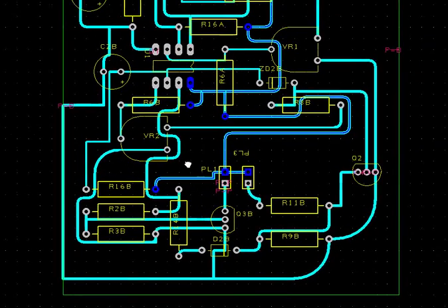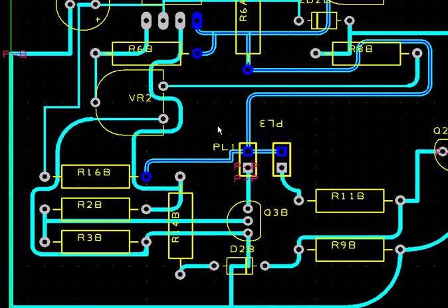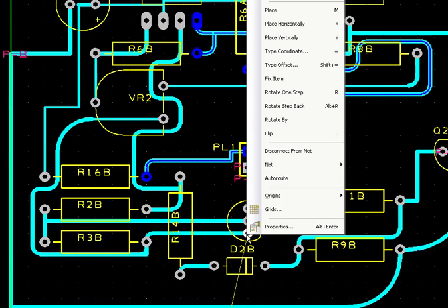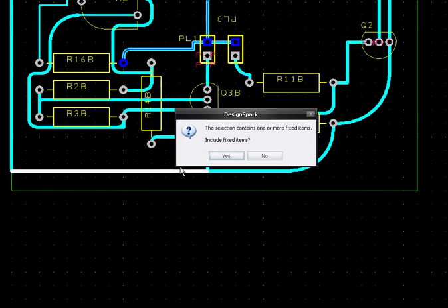So it's a bit like a game actually, but it's something functional. Right, I'm just going to type these up. And reroute that. That's a straight line now. That's better. Right, we've got that moved down. We've managed to get a track down between that variable resistor and down to the IC where we wanted it, without having that link which I took out earlier. So now I can move this track back up again a bit.